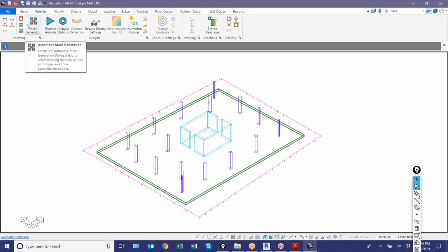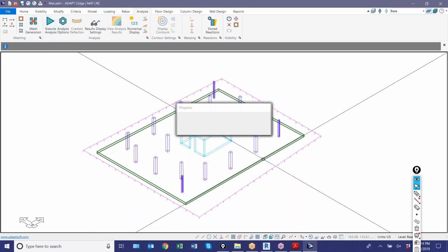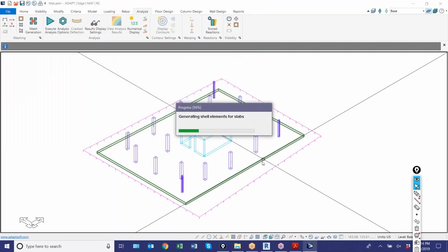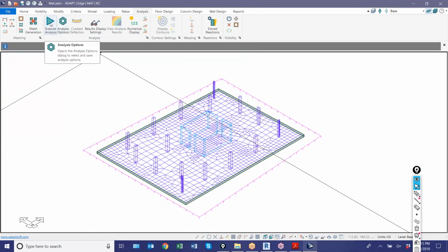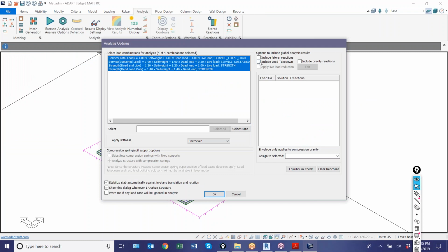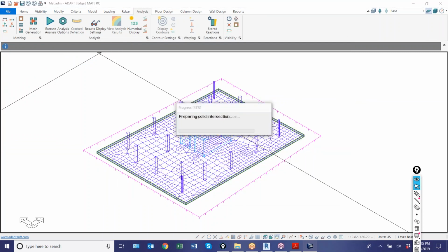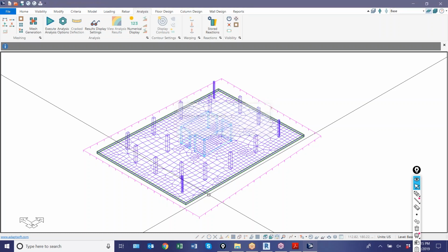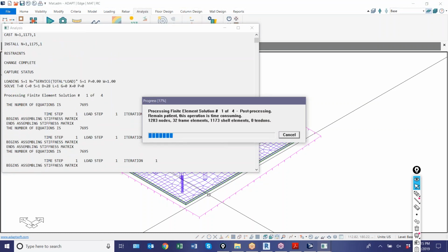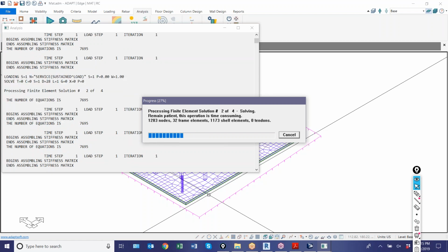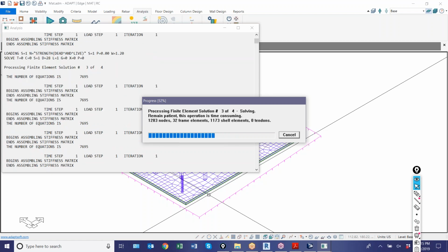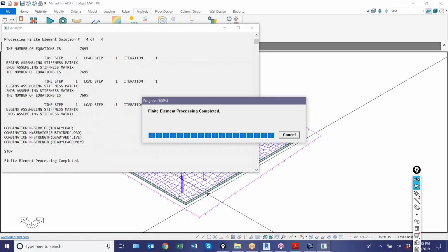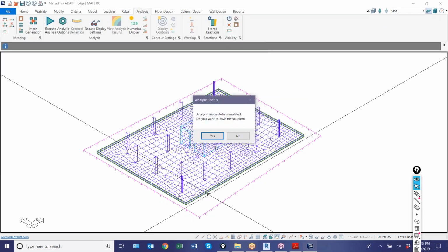If I analyze this level now, I'll just mesh this one level aside from the entire building, and I apply the reactions. If I execute the analysis, I can apply the reactions from tributary to this level. I've applied the reactions, and now I could evaluate, let's say, the soil pressure and design this mat based on those reactions, if that was what you're after. I mean, we might also want to include lateral load, which would require us to tap into the finite element engine. But in this case, I could utilize tributary for all of my axial forces.